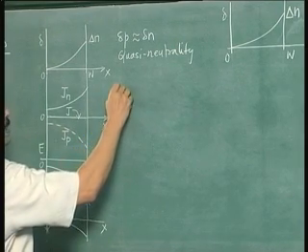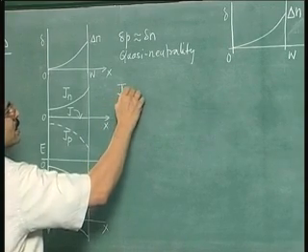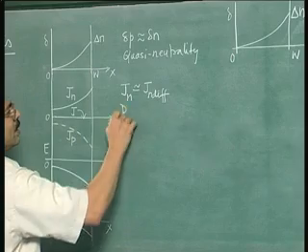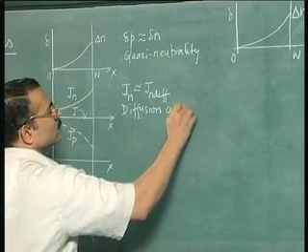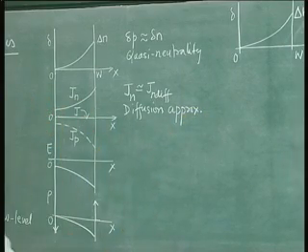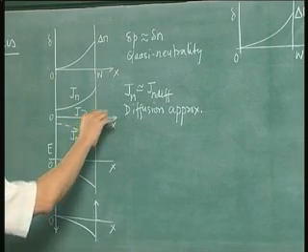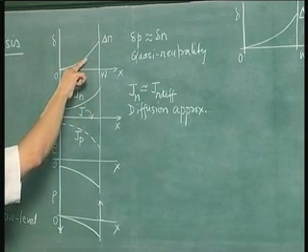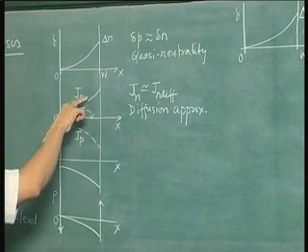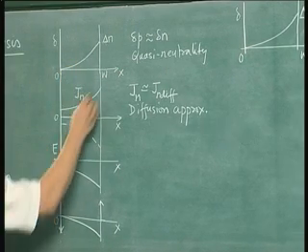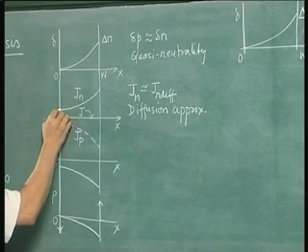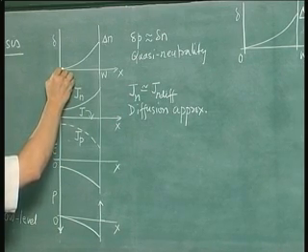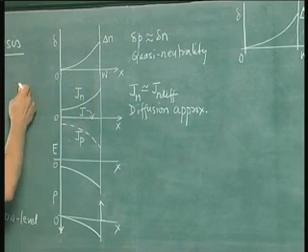If you make the diffusion approximation for minority carriers, that is Jn, the electron current in a p-type semiconductor, is approximately equal to the current because of diffusion. That is the assumption we are making. Please note that this holds only for minority carriers. We will prove at the end that this holds, but now we will make the assumption. Then the electron current can be obtained from the slope of this distribution, because diffusion current is the diffusion coefficient multiplied by the slope of the excess carrier concentration. So this is Jn. Note that Jn is not 0 here. This is because the slope of the excess carrier distribution here is not 0. We have discussed earlier that the slope is 0 only when the sample is infinitely long or very long compared to the diffusion length.